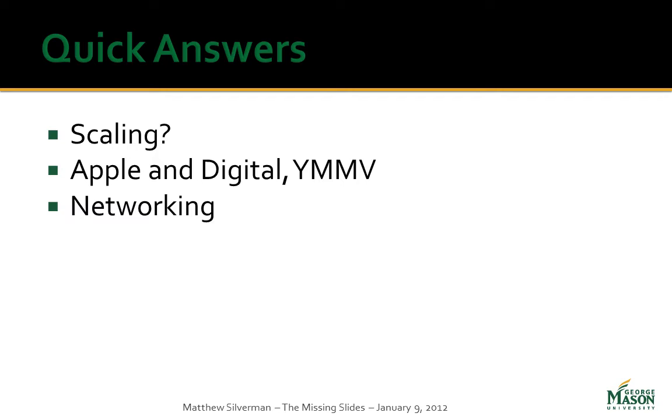Networking, just wanted to touch on this a little. Got a couple of questions about how do you configure your network, particularly for Crestron digital media, but also what happens if your network goes down. This has been a real concern, and it's both a Crestron product issue, but I think as you look at the other products which are coming out, which provide these solutions, Crestron's digital media product in particular requires a network to communicate. They've gone away from the proprietary CresNet bus and are now using TCP/IP communications for system communication.